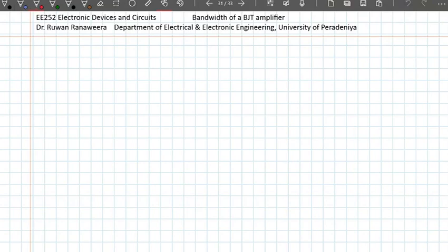If the load resistance, let's say, is 1K and my output impedance R out is like 40K or something, or greater than 10K, then, because now we have two resistors in parallel, RO and RL, if RO is much bigger than RL, then we can assume RL is the only one in that pair, and the effect of RO will be very small.